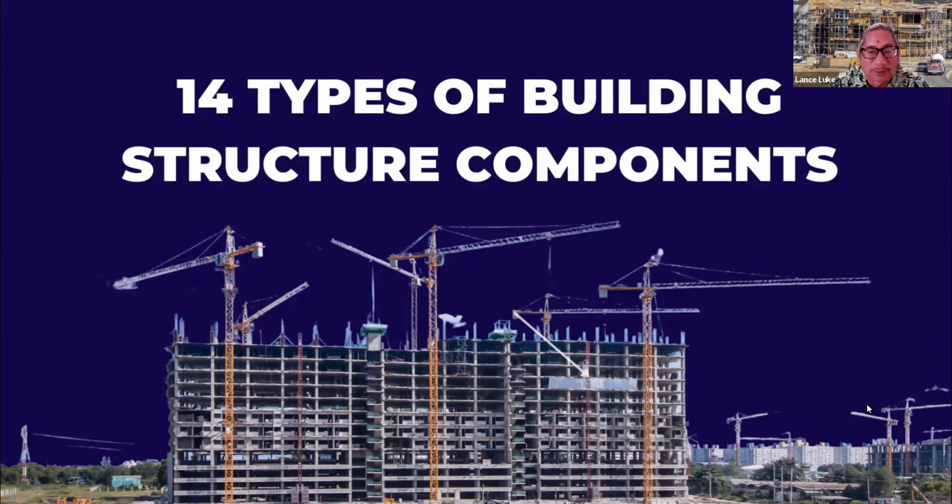Well, when I say you, unless you're the contractor, you're not going to be the one doing it. You hire a contractor to do that. So typically the foundation walls are made of steel, concrete, or masonry, which is basically hollow tile CMU blocks with rebar and filled in grout. So the hollow tile holes are filled in, and that forms your foundation wall. And then next, let's say it's a 2-story building, so your walls are up 2 stories. What happens next?